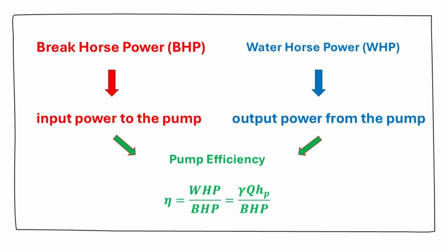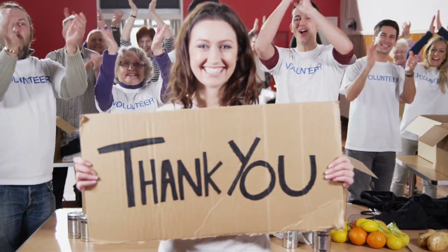Because WHP can actually be calculated using the pump head in operating discharge, and the operating pump efficiency can be estimated once we have the operating point figured out, the BHP can be calculated indirectly, although it can also be read from the brake horsepower curve.